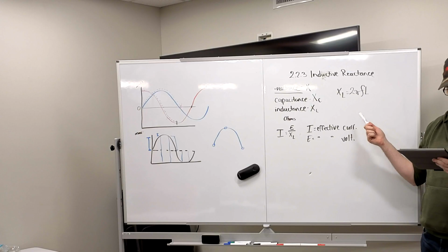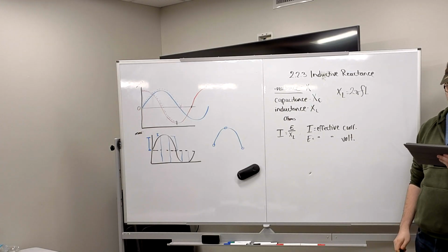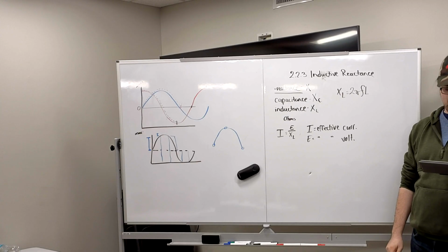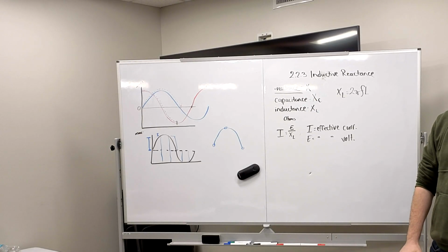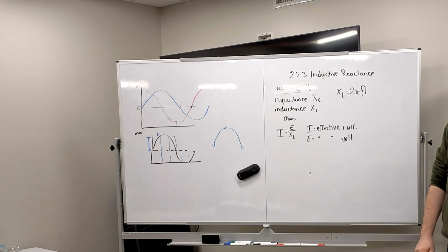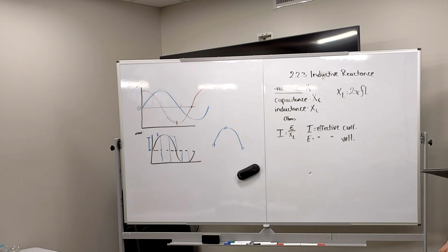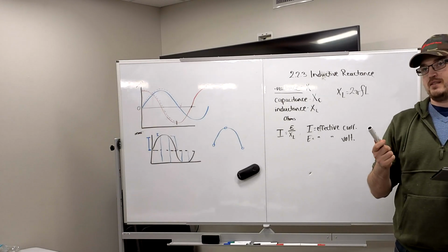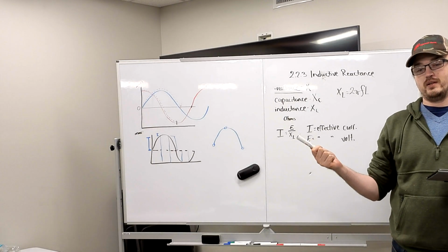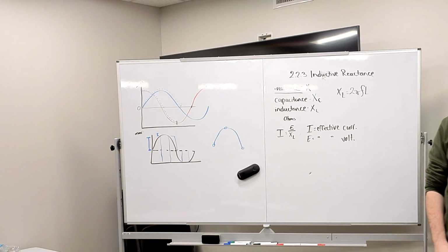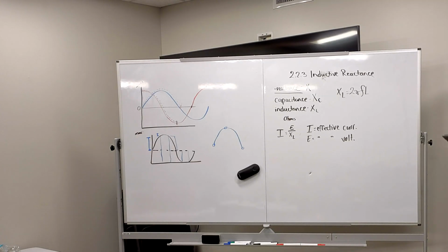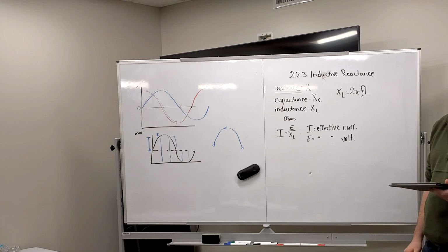Unlike a resistor, there is no power dissipation in an ideal inductor. Why? As in, power comes in, power goes out. Is that what power dissipation is? The reason nothing comes out the other end of that perfect resistor is because it's 100% dissipated, meaning it's all used up. So in an inductor it's not all used up. How much of it is used up? None.